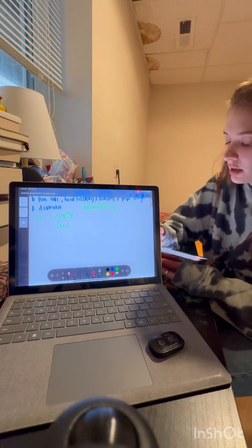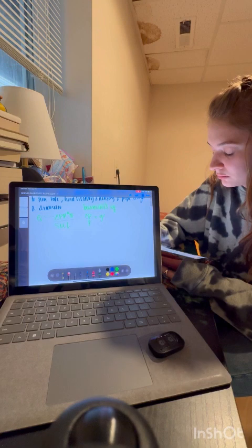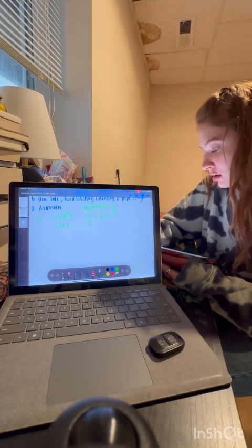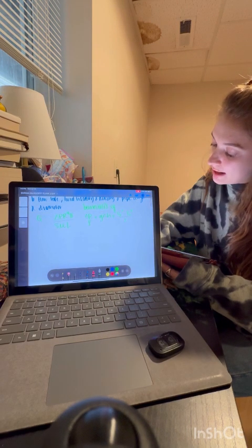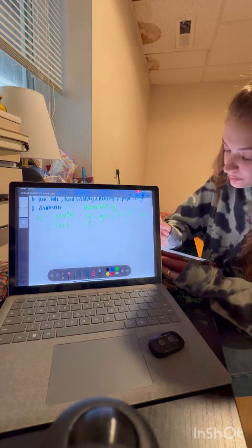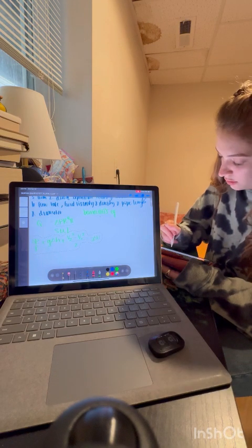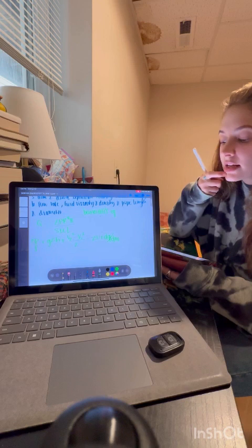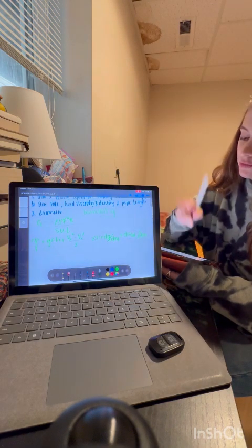That is a change in pressure over density plus gravity times change in height plus your difference in velocities squared divided by 2 is equal to your negative internal energy plus your differential heat with respect to your mass, plus your differential work from non-flow over your mass. Okay, glad I remembered that one.